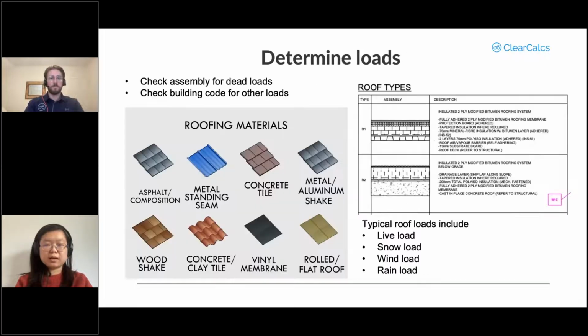And so once we have our schematic roof type, we have to determine what type of loads go on it. Depending on the final finishes, the dead loads on the roof will be different. There are rules of thumb based on what generally goes on top of a residential construction roof.